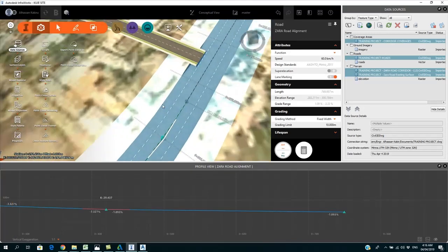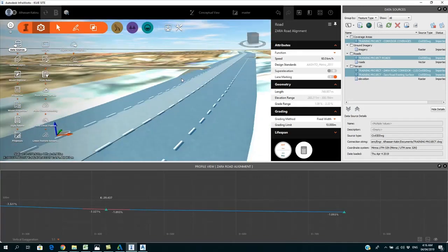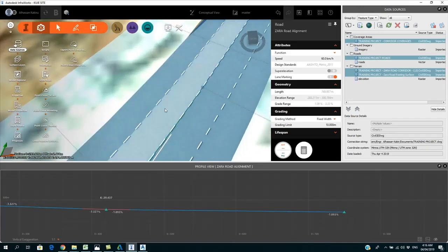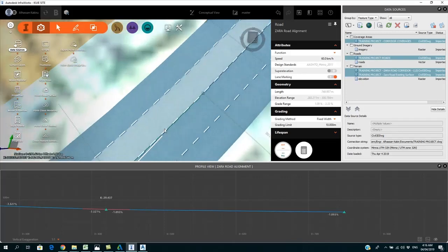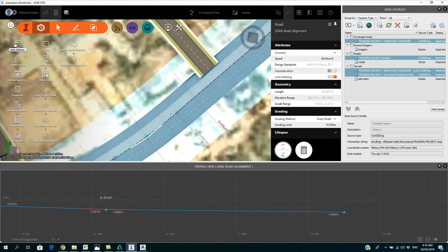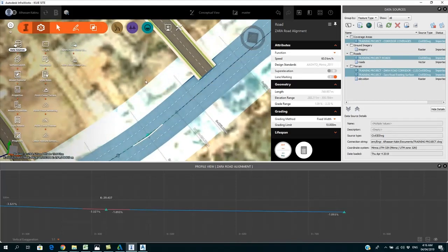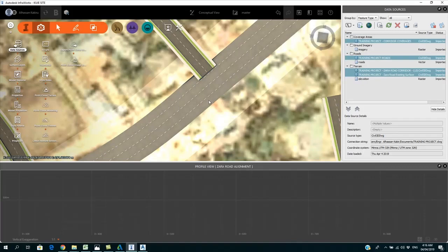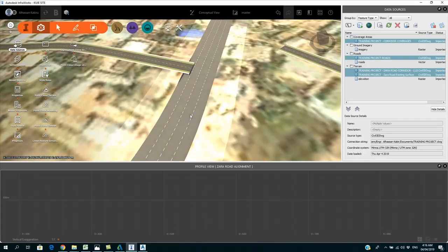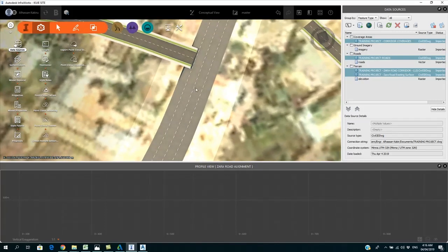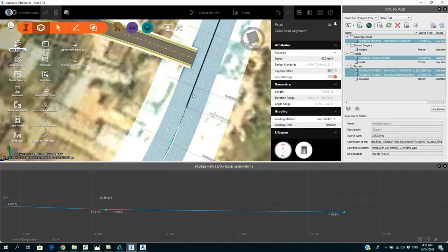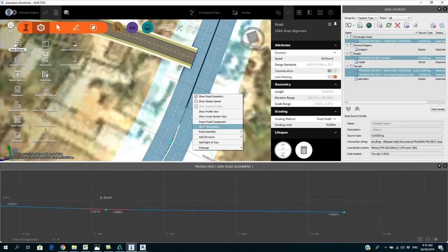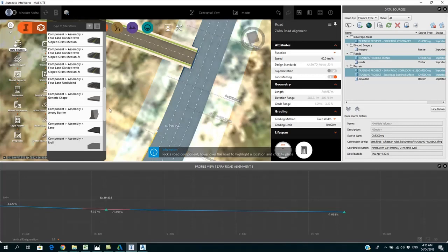So how can I modify my tools here? For instance, I decide that, okay, for this street road, I want you to have a median. Considerations to modify it, well, I just use this to explain the workflow. Then to have the median that have street lights. At the same time, I want to have that single carriageway and also have the drainage infrastructure. So in this case, what I will do is click on it and adjust the settings by creating add road components. The road component I'm adding is the median.